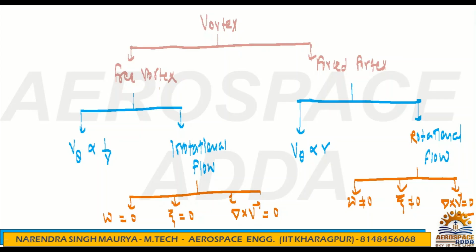Okay, always remember this. Also they can ask, because question from here they are asking. Okay, kinematics, this is the kinematics part. So always remember, in case of the free vortex flow, Bernoulli equation or energy equation will work here. Bernoulli equation you can apply in free vortex here, but in case of forced vortex, Bernoulli equation you cannot apply.